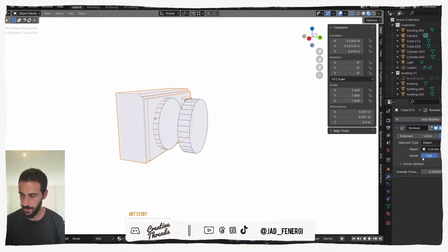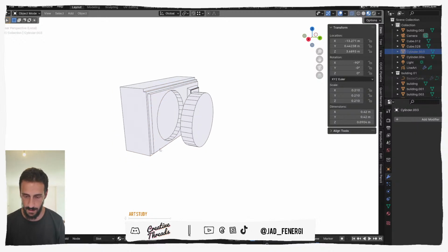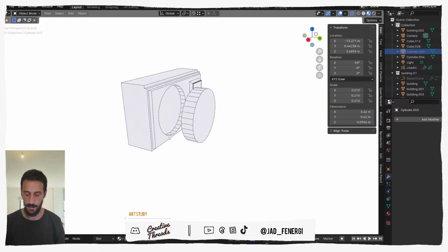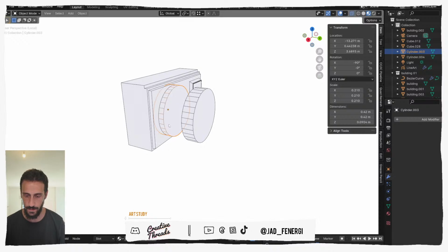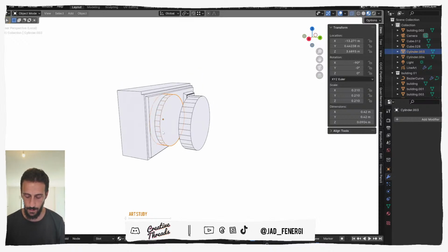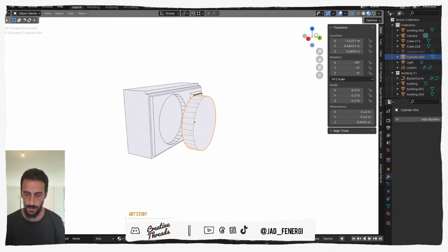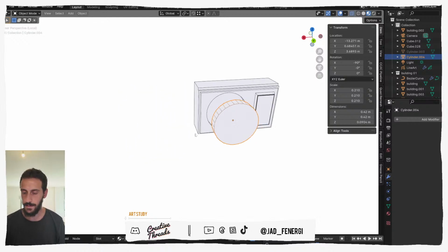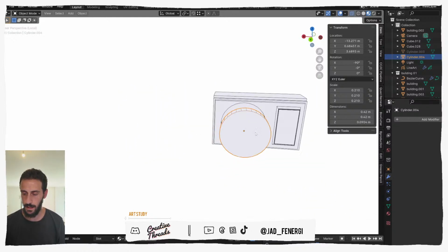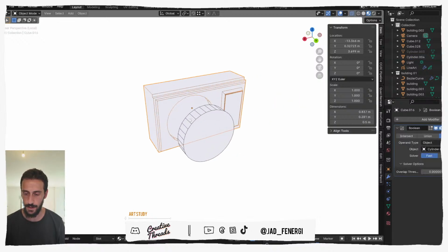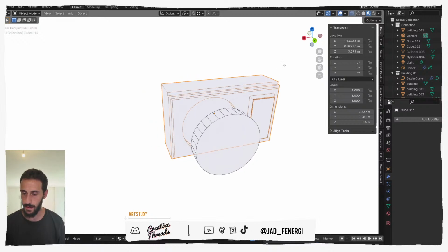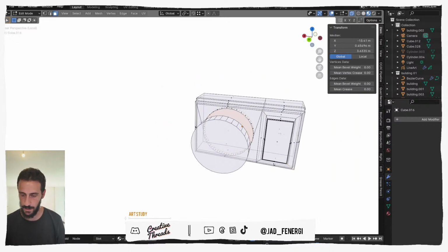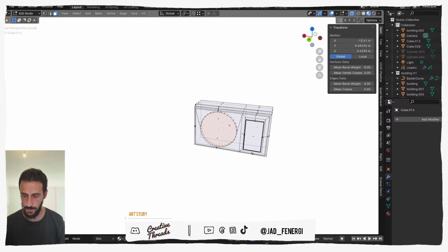I think we're gonna go for fast. Let's hide this. Okay, so the cool thing is that Blender keeps the object, but I think if you move it, you move the Boolean as well. So you cannot touch it. That's fine. That's actually not a bad solution. I think I'm gonna apply it just so we can solve some of the issues. Let's hide this for now.